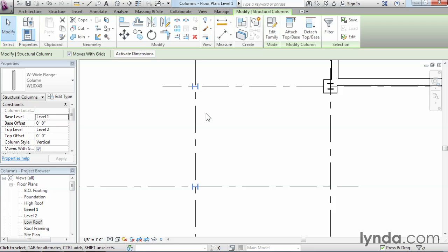In this movie, we looked at both architectural and structural columns. Typically, the structural columns are going to be used for the actual structural material, what's physically holding up the building. The presence of architectural columns is optional. It can be used as column wrap enclosures, or they can actually be used as temporary stand-in locations for the columns that are later replaced by your structural engineer. The exact workflow is a matter for the team to decide, but both columns share the behavior that they are attached to the column grid, and if the column grid lines move, it takes the columns along with it.